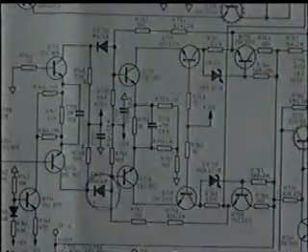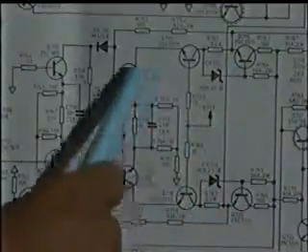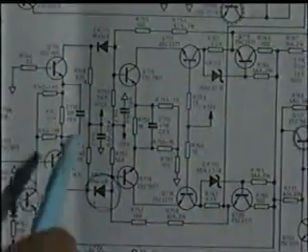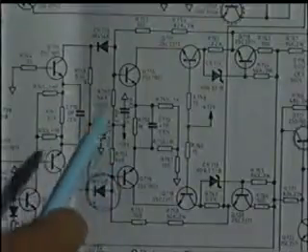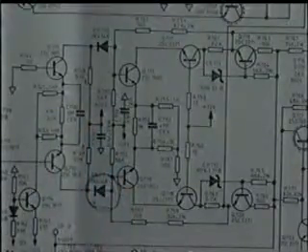Therefore, any defective transistor will change the voltages at every point of emitter, base and collector of each transistor. In this situation, when all transistors are DC coupled, it is very difficult to find out the defective transistor, because the voltage at each and every point of the transistors, emitter, base, collector, will be different compared to the prescription in the manual. To find out the defective transistor,